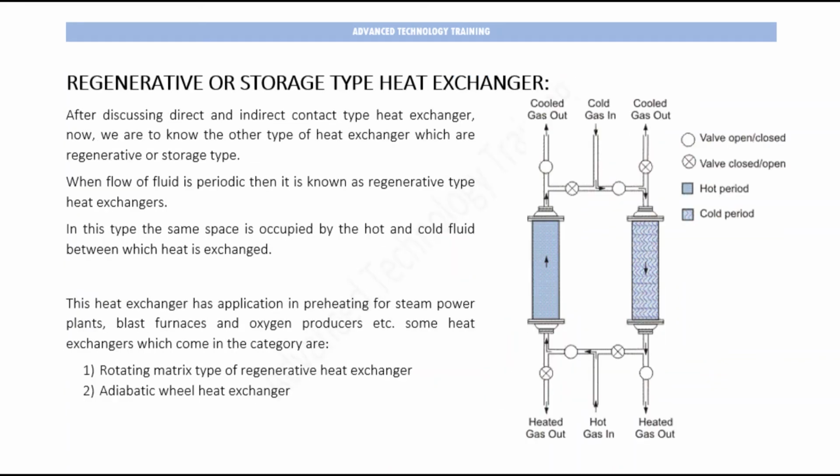Regenerative or storage type heat exchanger. After discussing direct and indirect contact type heat exchangers, now we are to know the other type of heat exchanger, which is regenerative or storage type. When the flow of fluid is periodic, it is known as a regenerative type heat exchanger. In this type, the same space is occupied by the hot and cold fluid between which heat is exchanged. This heat exchanger has application in preheating for steam power plants, blast furnaces, and oxygen producers, etc.